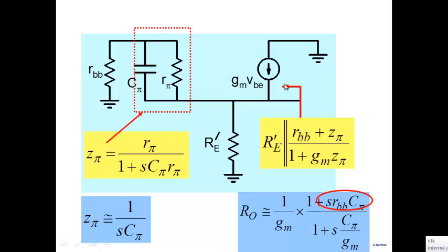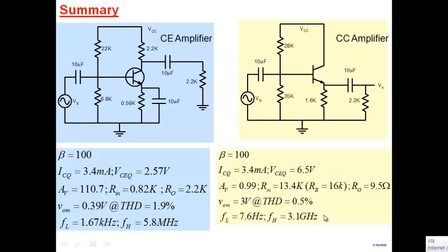So all you need to do is write down what is the net impedance looking from here. And if you examine it, you find terms like this, which give rise to inductive behavior. All right. So with that, let me summarize the common collector amplifier, a slide which we've already seen, especially contrasting it with the common emitter amplifier.